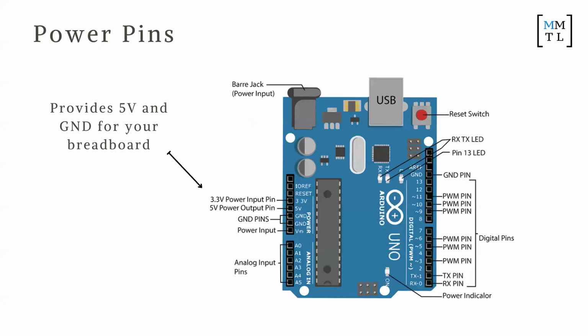All right, now how do you actually power your breadboard? Okay, so the breadboard obviously by itself doesn't have any power, it's merely a board rack, but you can actually power it by connecting the 5-volt and the ground pins to the plus and minus strips of your breadboard, okay? So I want you to do that first up, which is connect these 5 volts and the ground pins to one side of your breadboard. Okay, so we're just going to go around and make sure, yeah, using the male-to-male connectors.